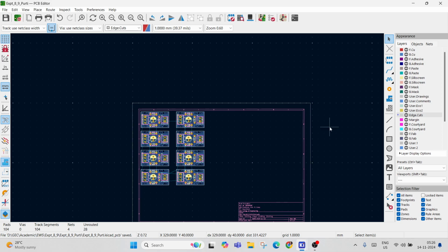Then the Gerber file has to get converted into a geometry file. Then the geometry file will get converted into a CNC job, which is G code. So Gerber to geometry to G code. Now, from PCB layout to Gerber is going to be converted by KiCad. From Gerber to geometry, and geometry to G code, is going to be done by FlatCAM.